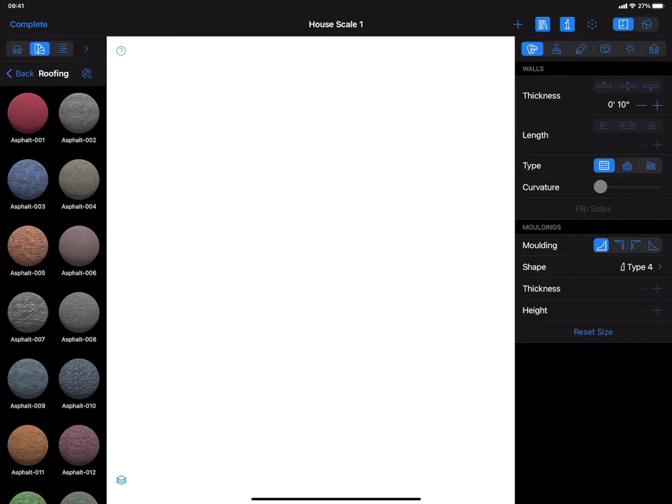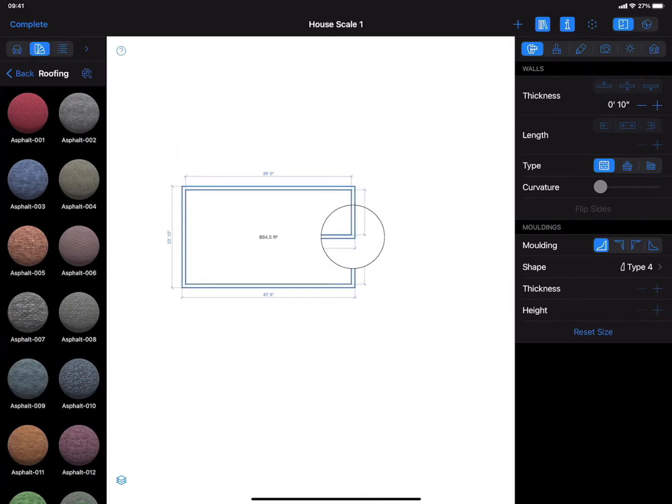The easiest way to draw a complete room is by using the Room tool. Once you activated it, tap on the floor plan and drag your finger along the floor plan. This will specify the position of a corner of the room. As you see, the program displays the length of each wall while you draw.